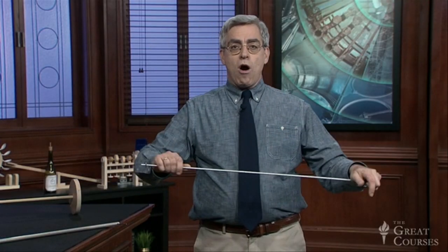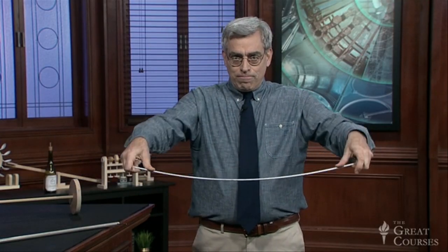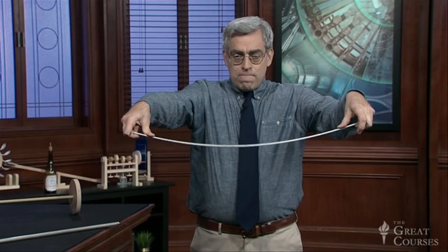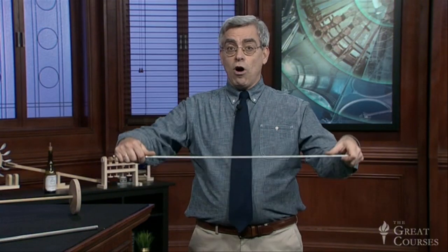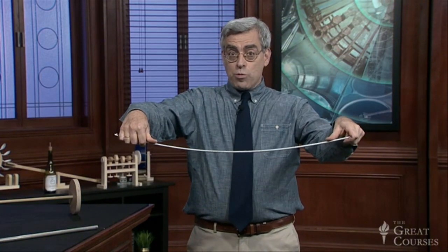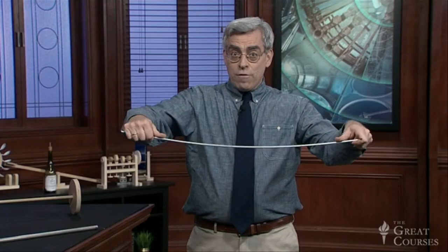The tube is also superior to the bar in bending. Again, I can bend this bar quite easily by hand, like this, but I can't budge the tube at all. This is really important because the drive shaft of a front-engine rear-drive car can be upwards of 5 feet long, sufficiently long for a solid bar to experience problems with both sagging, like this, and vibration.